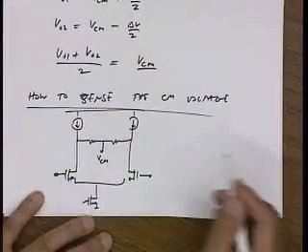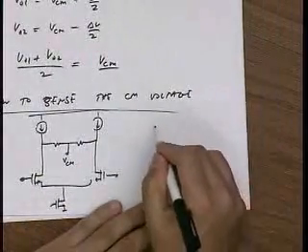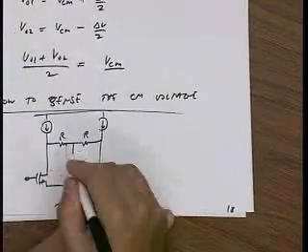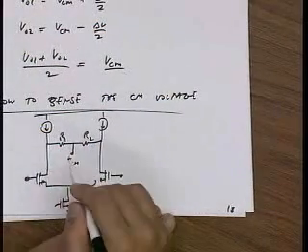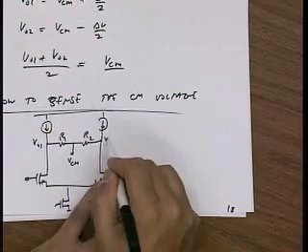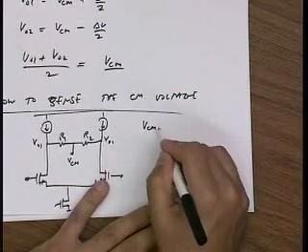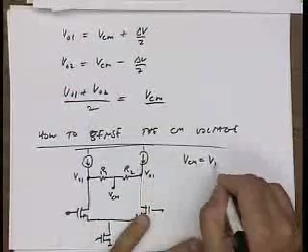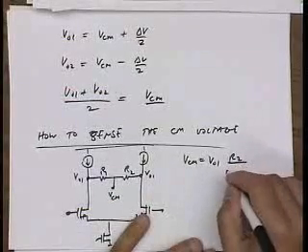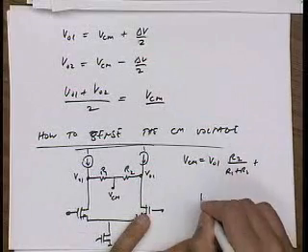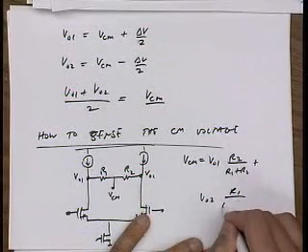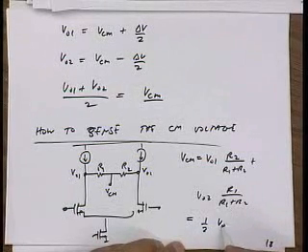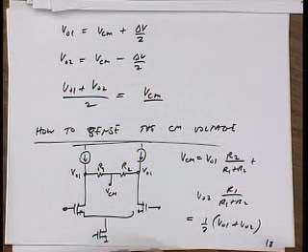But, okay, so this is going to sense my common mode, right? And the way it works is it's basically a voltage divider, right? If this is R1, this is R2, this is VO1, this is VO2, VCM is VO1 R2 over R1 plus R2 plus VO2 R1 over R1 plus R2, and if these are equal size resistors, it's just 1/2 VO1 plus VO2.